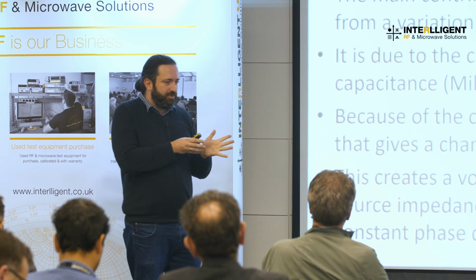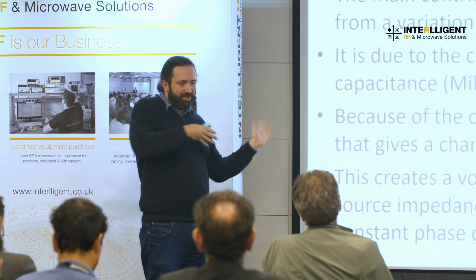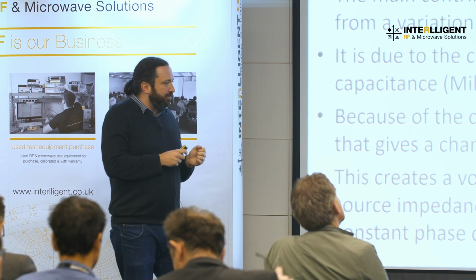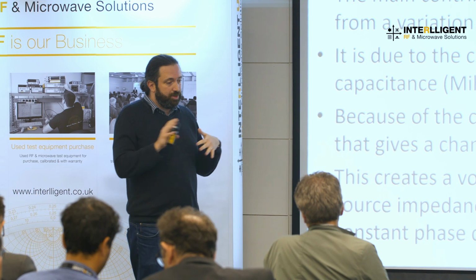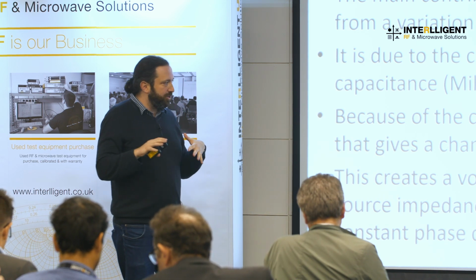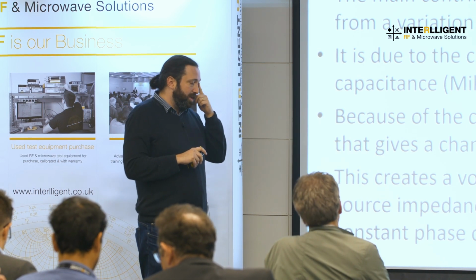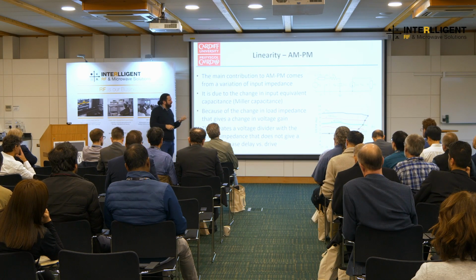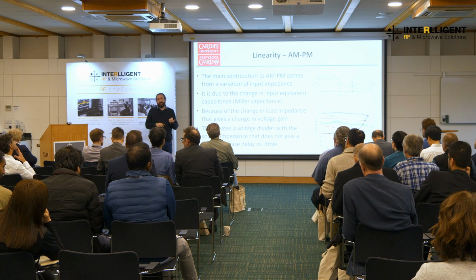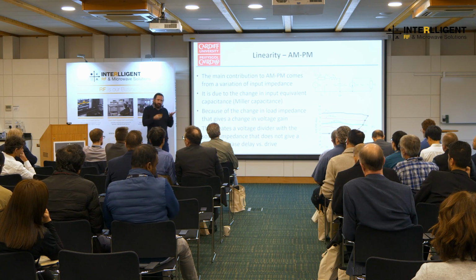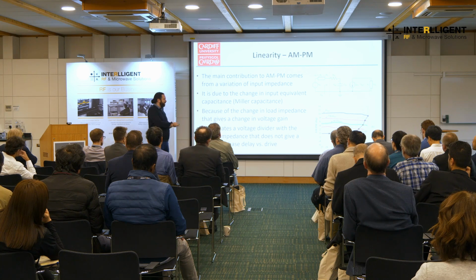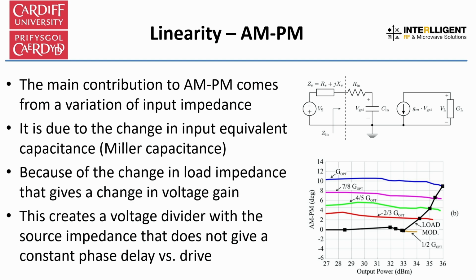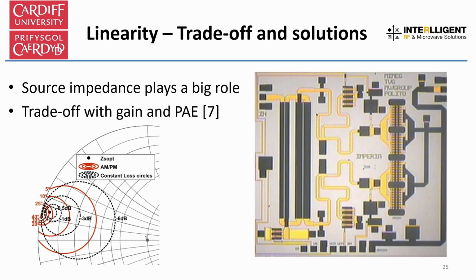Now, you can do strange things like not making the currents perfectly align in phase, and you can adjust a little bit. But if you have the Doherty that works as you should be doing, giving you the good IM and good efficiency, then you have a distortion in phase. What can you do to mitigate that? Well, you can mismatch the input again, but we lose gain, okay? So that's your compromise, really, it seems to be always ending up there between gain and phase distortion or distortion in general. We actually tried that.